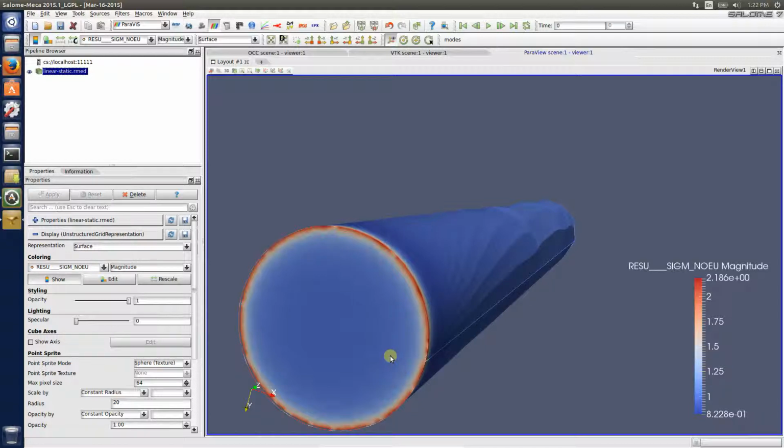that stress is a simple result of you gluing the entire surface. The way I've done it, all this is fixed. Essentially, I put crazy glue out, stuck the thing on the table and let it glue. And then I go along and push it. Well, it's pushing, and yeah, there's some stress. If you look at the little cube down there, you'll see there's some normal stress. But you'll also see that there is some stress in this direction, holding this thing on, because the table, or whatever I glued it on, is holding the bottom of it so that it doesn't expand.